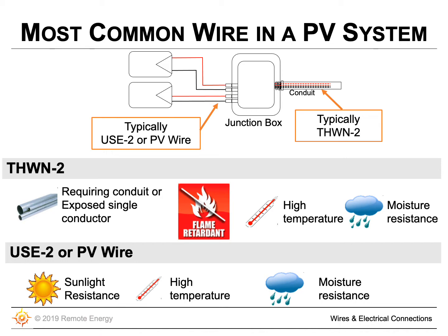So you can see a bunch of letters there in the middle, the THWN-2. Each of those letters represents a different function of the insulation around the wire, and we're going to get into that momentarily. But looking at that THWN-2, that's a single conductor type wire, and it's usually used somewhere in conduit.